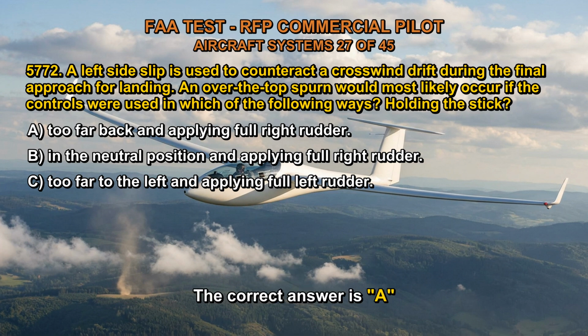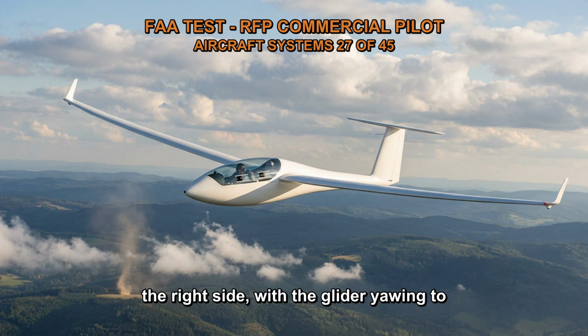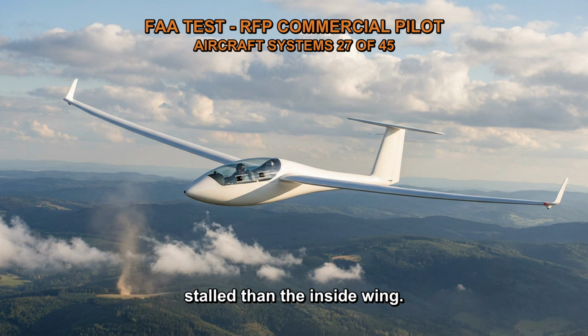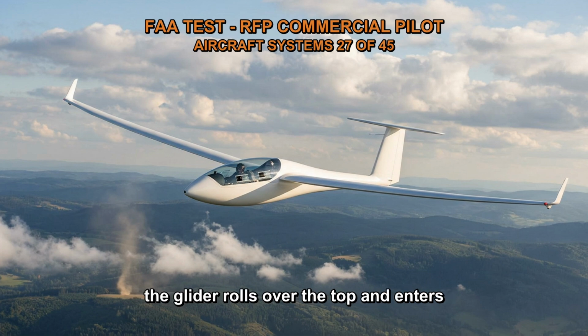The correct answer is A. If the controls are used in this manner, it would result in an excessive slip to the right side, with the glider yawing to the right and the nose pointing to the left. This can create a condition known as a skidding turn, where the outside wing is more stalled than the inside wing. If the skidding turn is not corrected promptly, it can lead to an over-the-top spin, where the glider rolls over the top and enters a spin.